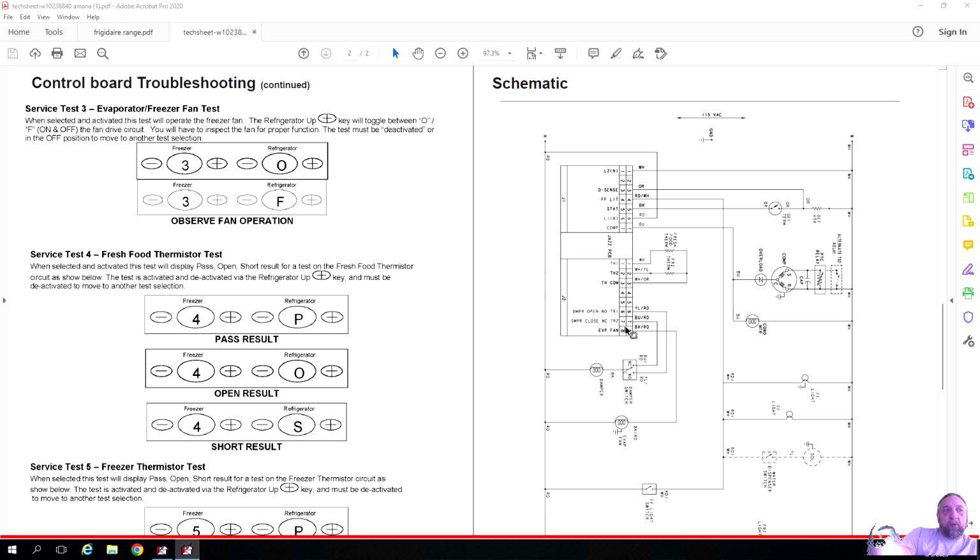So why is the board in two different pieces that we're here looking at? It's engineering, but if you notice, most of the components on J2 are low voltage. Most of the components on J1 are 120 volts. So our lights, our defrost circuit, our compressor, everything is running off of J1, but on J2 we've got our sensors, our damper motor.